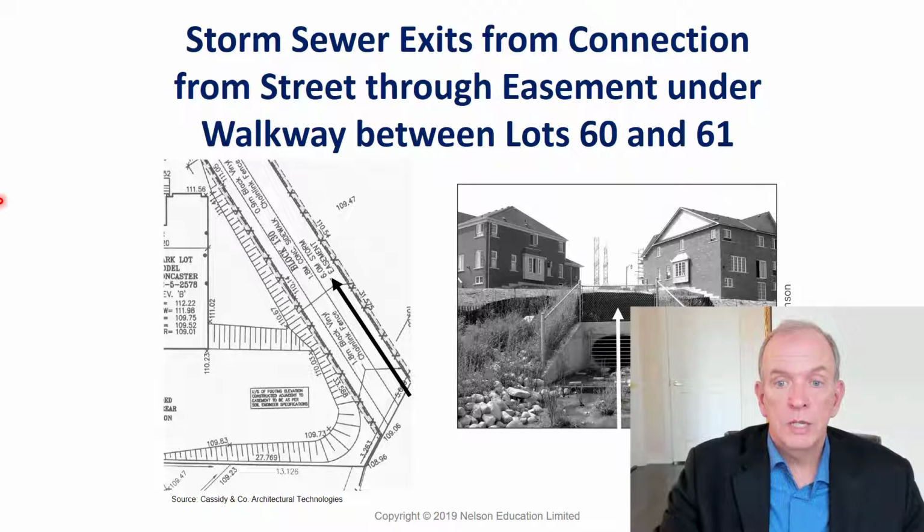This is that stormwater easement that I mentioned. So I'm standing kind of in the drainage area there, and that drainage sewer from the stormwater sewer is taking all the water from the street, those catch basins I showed you earlier, and other ones around the neighborhood, and it's feeding it into this drain here, stormwater drain, and it's going out into the tributary, and that's going out down the tributary creek, and eventually goes into the lake.